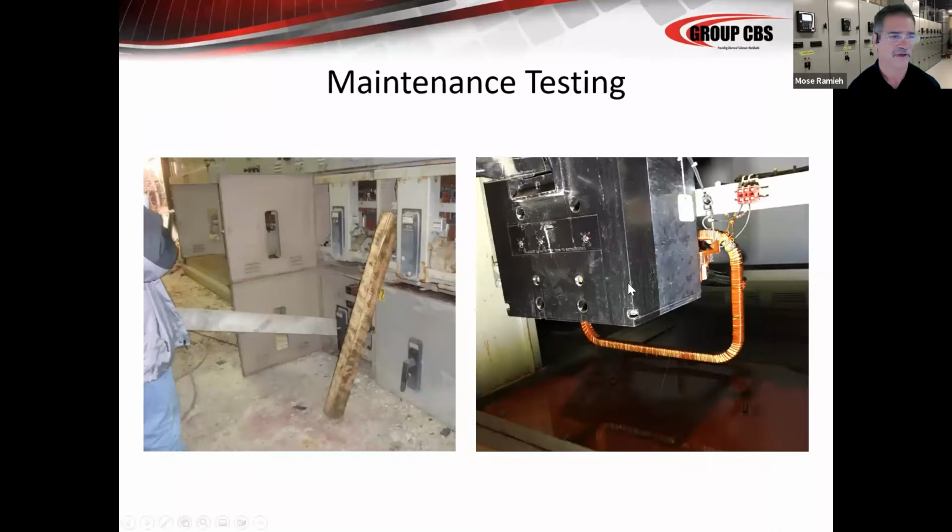The other thing we find oftentimes when we're doing maintenance is that any electrical or mechanical piece of equipment can fail at any time for no apparent reason. Here's a great example of a residual neutral CT that's part of the ground fault system for this breaker. And it's an ITE CT, and ITE is notorious for having what they call the ITE melt. Essentially, the casing of the CT just melts away, and it's not related to heat. It's strangely related to humidity and the age of the equipment, because this is aged equipment to be sure.